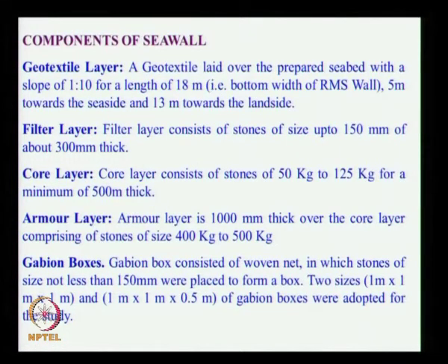Suppose you have a clay, then after putting a geotextile filter it is better to put a sand and then put a stone, depending on the subsoil condition the filter layer varies. Then we have a core layer. So this is the size of the stone and this is the thickness of the core layer.